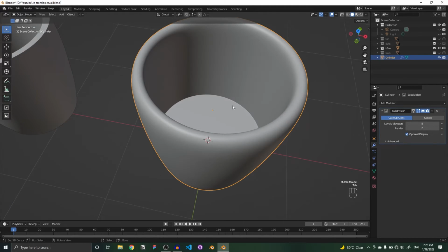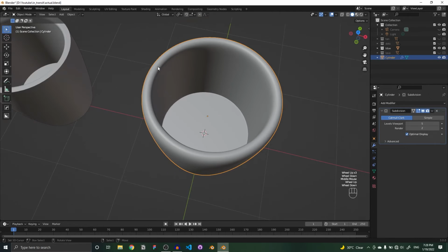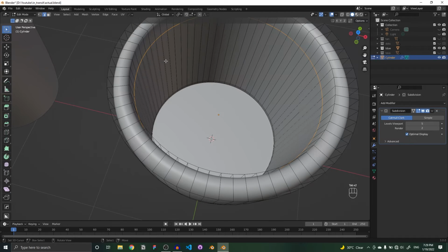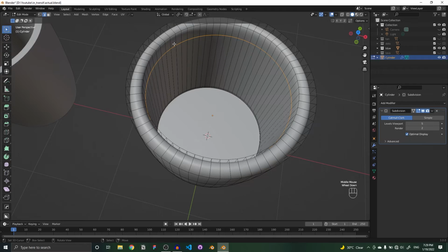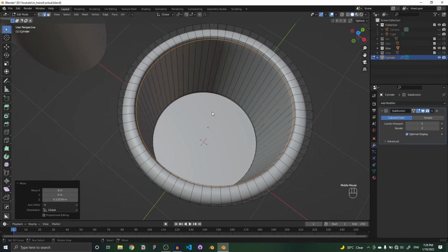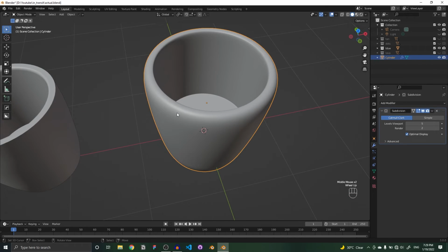All right, tab and go to the object mode. As you can see, it's taking shape. Maybe we prefer to have it a little more widthwise. So Control Z, tab, edit mode, and okay, when I pressed Control Z, I selected the loop cut by mistake. So you can select it again and then press G, then Z to move it along the Z axis. Now go to the object mode. It's taking shape. We can do the same with the outside so that we have a strong outer edge.